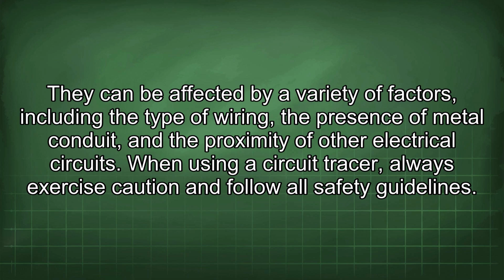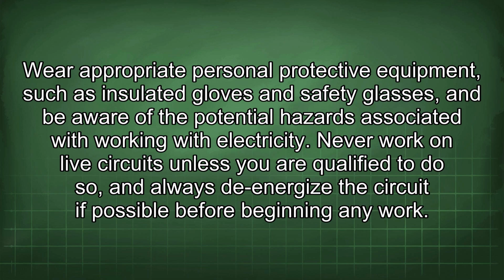When using a circuit tracer, always exercise caution and follow all safety guidelines. Wear appropriate personal protective equipment, such as insulated gloves and safety glasses, and be aware of the potential hazards associated with working with electricity. Never work on live circuits unless you are qualified to do so, and always de-energize the circuit if possible before beginning any work.